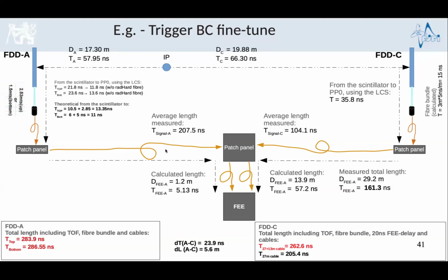So in this case, to align all the signals to the front end, all these cables had to be measured very precisely and cut in order to have less than, around, 1 nanosecond precision on the propagation of the signals, even better than that, in order to induce as few errors as possible in all these cables.